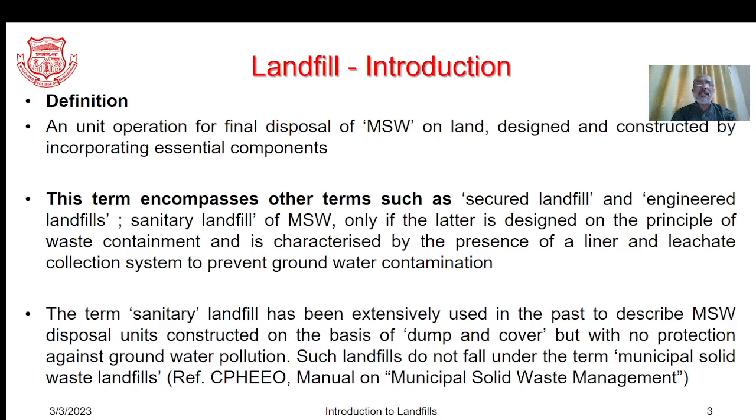According to modern terminologies, whatever term we are using as a landfill is at par with secure landfill, engineered landfill, sanitary landfill, only if the landfill is designed on the principle of waste containment and is characterized by the presence of essential components which do not allow percolation of the products that are developed in the various processes that take place during the storage of the solid waste.